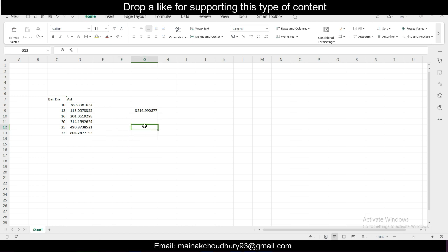If you want to substitute by 25 mm bars, it will be this divided by 25, for example. So it will be 6 point something. We cannot give 6 point something. We can give 8, or we can give 4 and 2 or something else like this. It's better to give even numbers because of the arrangement.